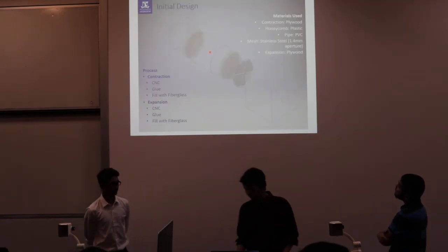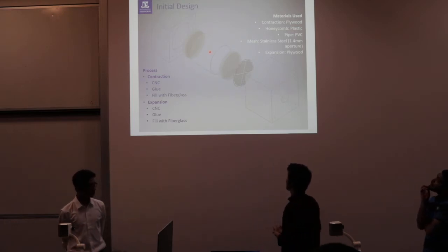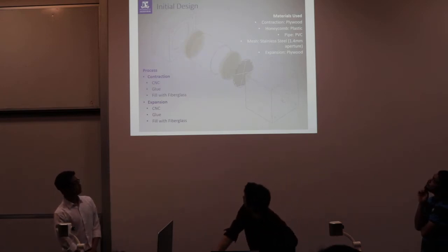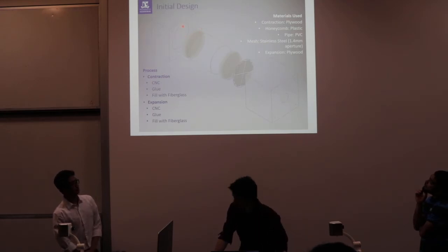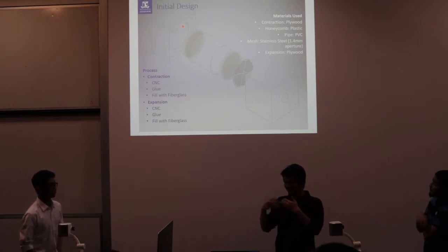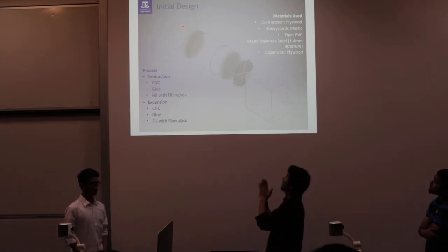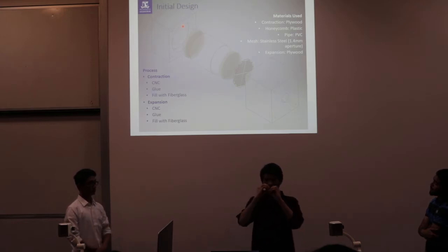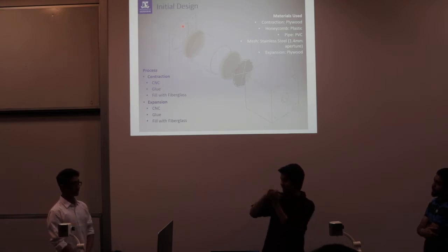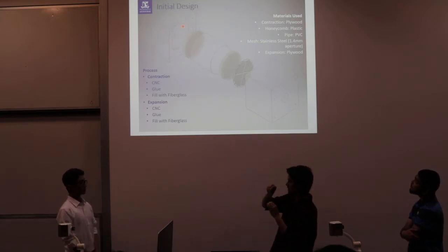Basically, as mentioned before, we want to minimize the eddy currents in the flow. That's why you can see the honeycomb mesh here. As the flow goes into the device, there are lots of eddies, and when it hits the first honeycomb, it squeezes the flow, so it squeezes the eddies. The flow goes smoothly through the honeycomb, and we use 2 honeycombs to make sure that it goes very straight.